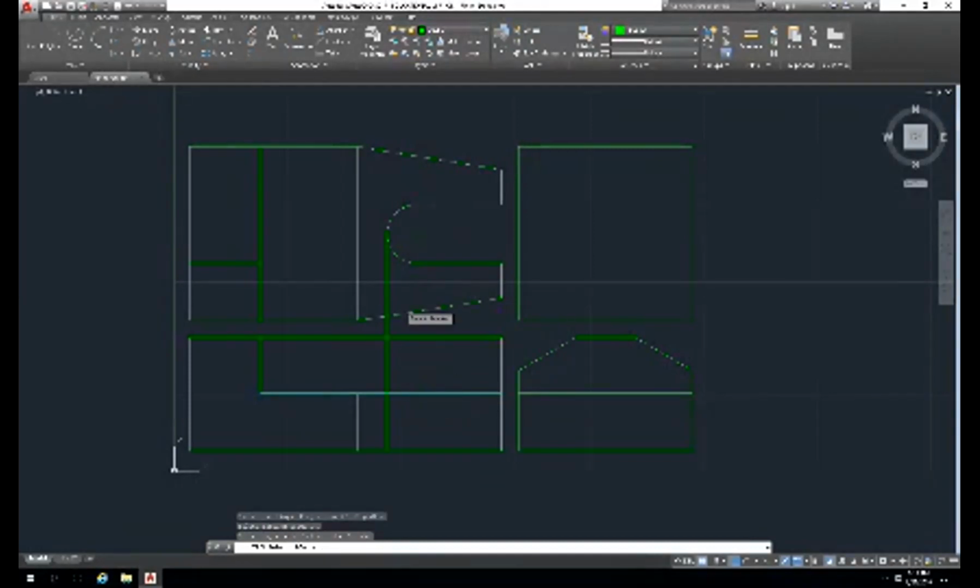So trim from here to here. And enter. Select the line and select it as a hidden layer. So there it is, yellow, but sometimes it shows up as an interrupted line and sometimes it doesn't. So now this whole chamfer rigmarole, we have to transfer that feature onto the right side projection. So once again, we're doing our lines. I'm going to do INT. There's my first line. There's my second line.